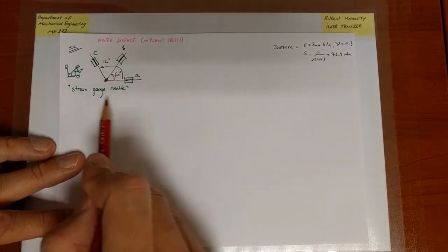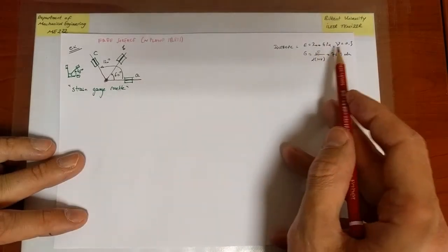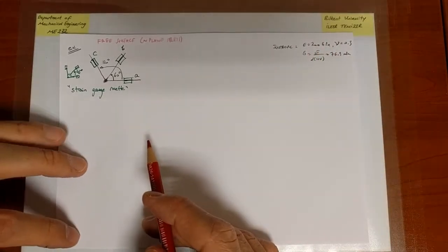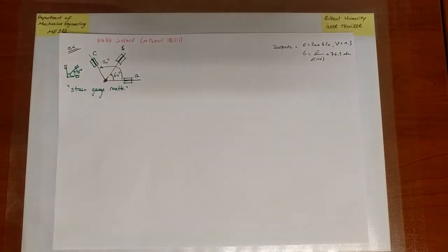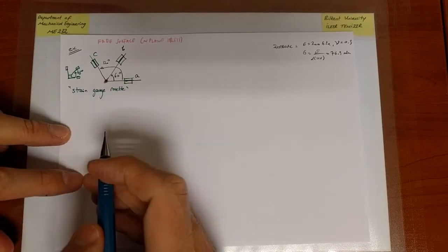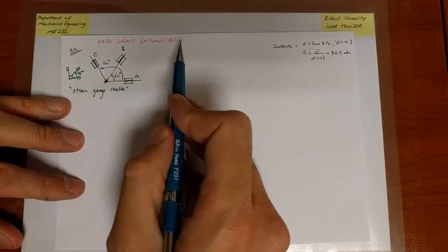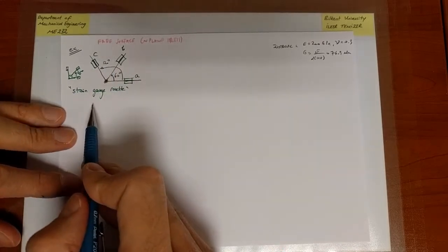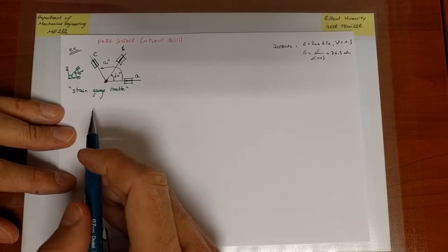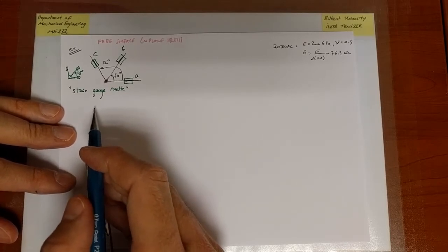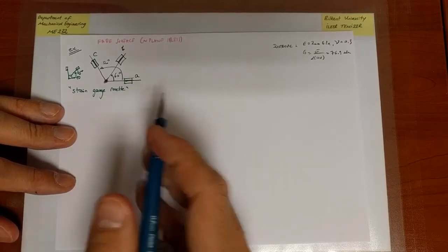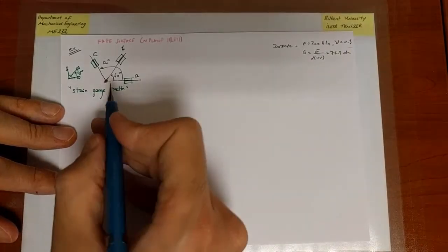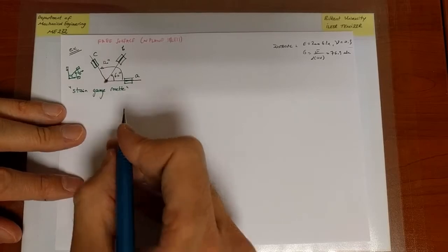And so on a free surface, you put a strain gauge. It is apparently a steel beam or steel structure. Could be a complicated structure, could be on a wing of an airplane, and eventually you're measuring the state of strain. It is a plane stress scenario, so keep in mind, it is not in fact in general a state of plane strain unless Poisson ratio is 0, which it is not, and therefore it's going to be a state of generalized plane strain.